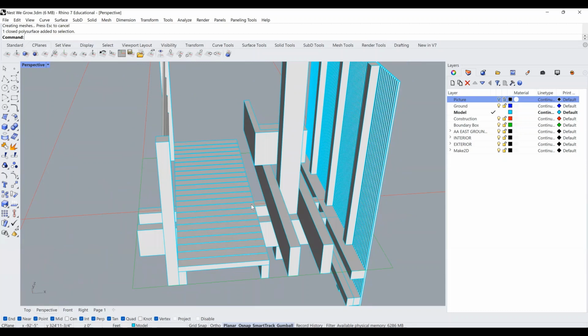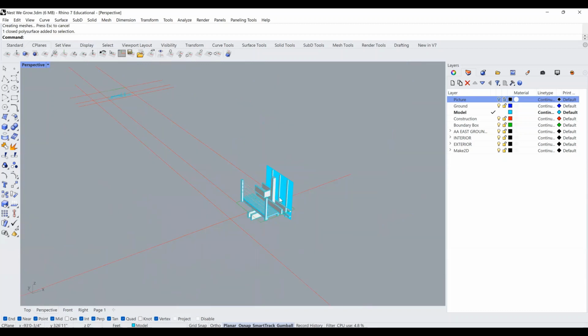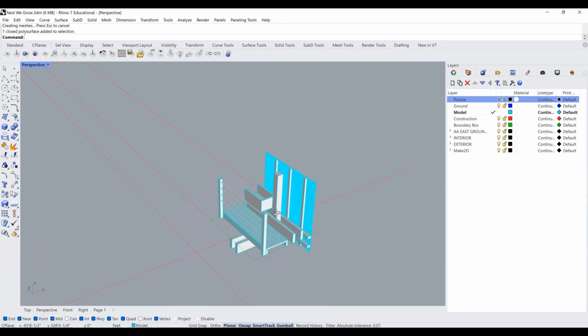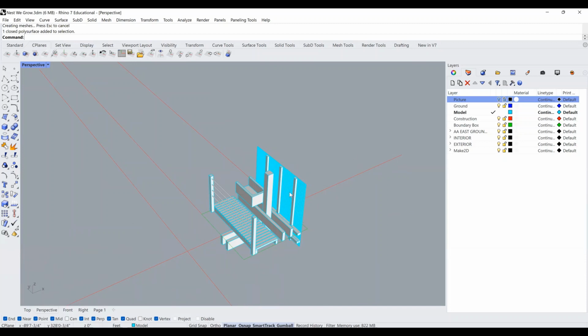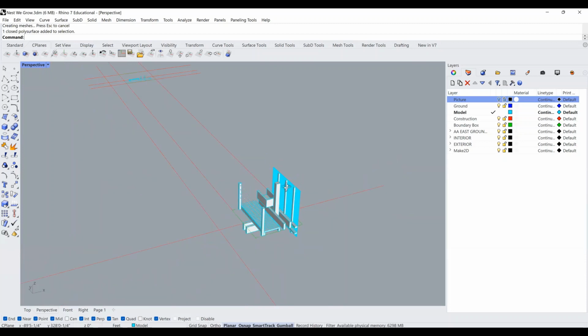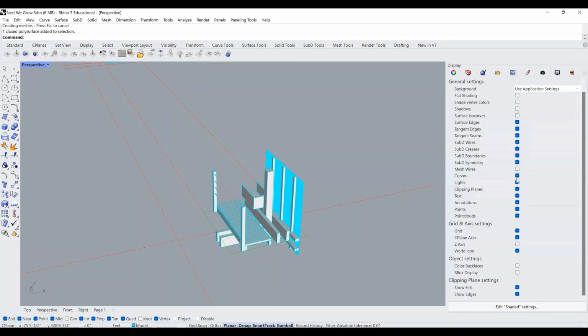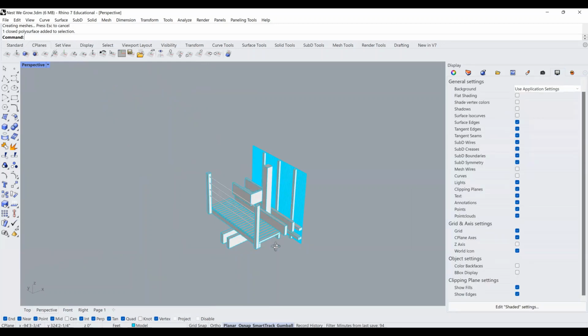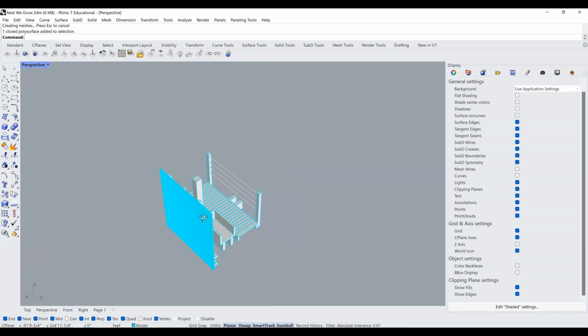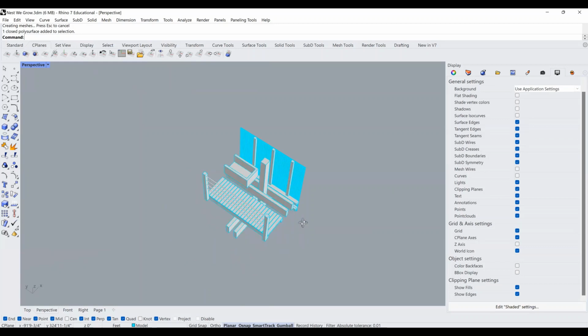And so with that, now you can start going on and making the Make 2D of this in order to present this in your final project, right? So the way I'm going to do this for now is that there are several tricks in Rhino that can help you increase your efficiency to do this. So I'm just going to turn off curves, and then I'm going to make an interior view and also an exterior view of this, right? In 180 degrees.